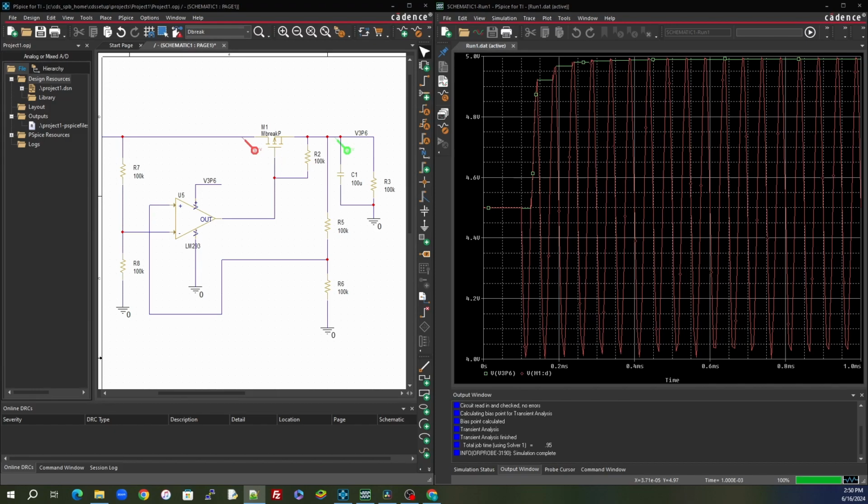Now there are a few things with the circuit that are still a little sketchy and need to be ironed out. I really didn't go into details on them. I've done them in other videos, but one, I didn't do a tolerance stack up on the resistors here, which I don't know if it'll be an issue or not. And two, I do not have any hysteresis built into this comparator. So when things are going, it may or may not be an issue in this particular one. But I'll let you guys decide on either one of those.